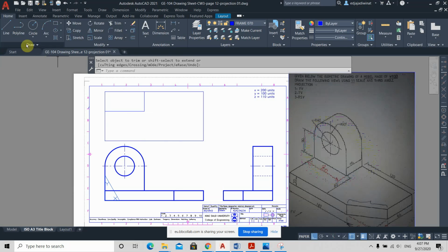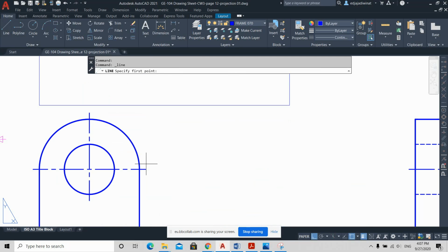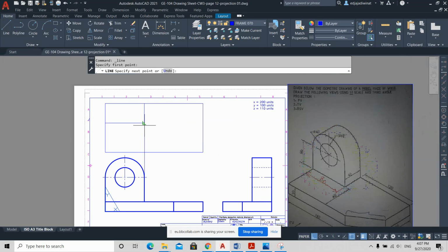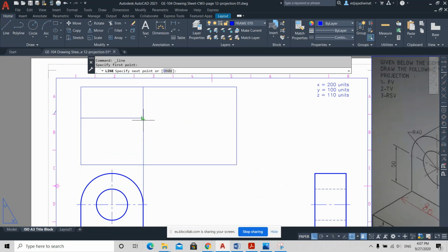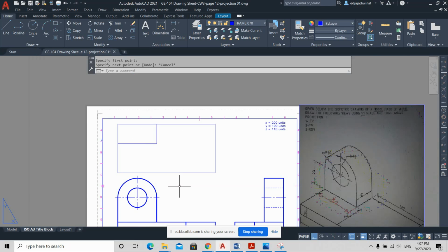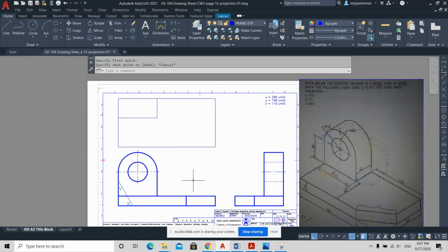So if you make this correctly, you enter the correct dimension, it has to be the same as the projected line. It has to be the same. That's why I prefer to use a projection, so you avoid a mistype when inputting the dimension.